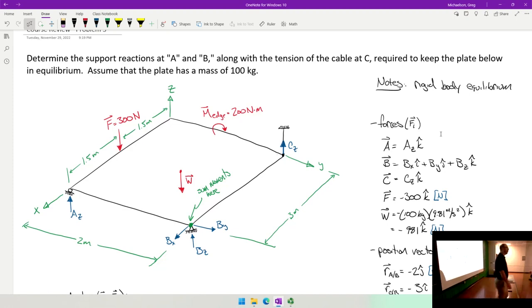How do I know, first off, what axis that's aligned towards, and whether or not that's a positive or negative moment? The answer is to use an incredibly bad amount of sketching and to use the right-hand rule. Notice how if my thumb points in the direction of the y-axis, I am pointing along the axis about which this moment is rotating.